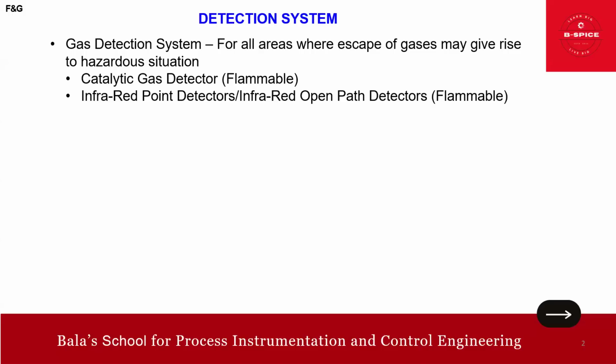Both types of detectors use infrared light. That is the point. They are immune to poisoning, resistant to corrosion, and do not require oxygen to operate, making them reliable and low maintenance options for gas detection. I hope you got some insight on this.